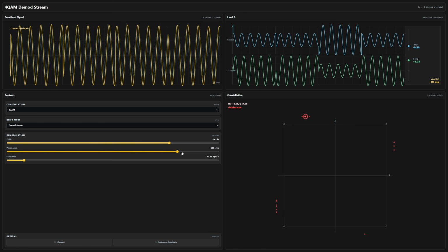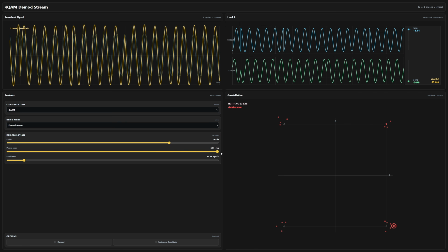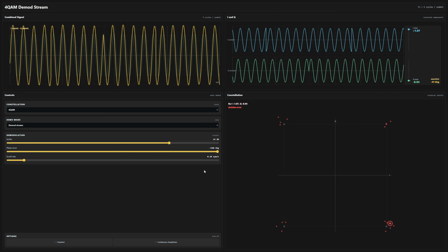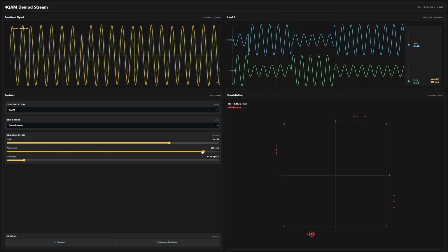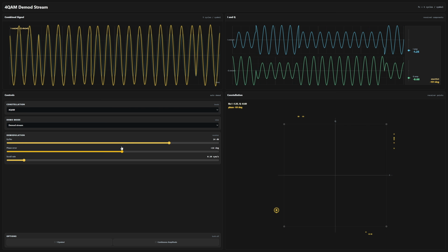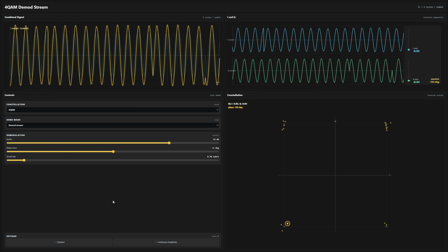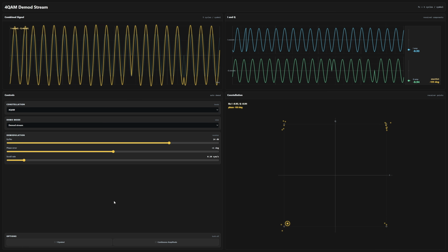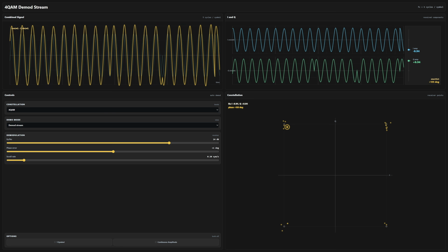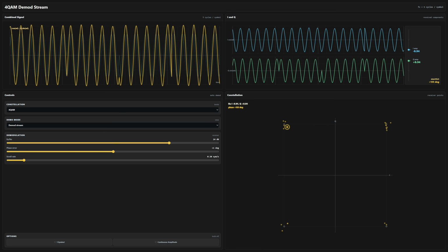If there is a 90-degree or 180-degree phase error on a symmetrical constellation like QPSK, the control system cannot simply correct it. To prevent this ambiguous phase, communication standards will include recognizable pilot sequences that the system can lock onto. Alternatively, instead of directly encoding a phase, the system will encode the bit with differential phase shifts and/or differential amplitude shifts. This is how coherent modulation works for RF.